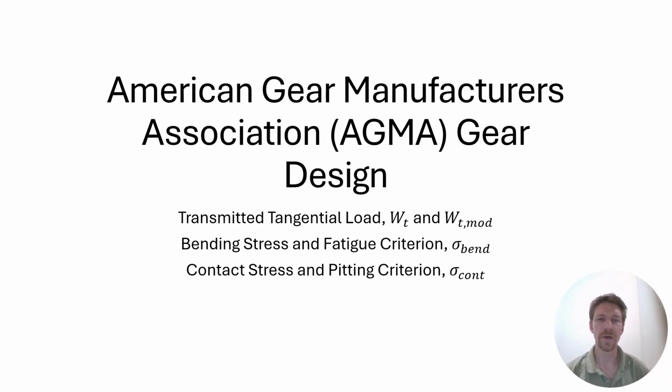What we're going to do right now is look at the American Gear Manufacturers Association AGMA gear design approach. It has three parts. First is the transmitted tangential load, WT, and then using several factors to modify that load to get WT modified. Then focusing on the bending stress and the fatigue criterion in bending, and then focusing on the contact stress and the pitting criterion.